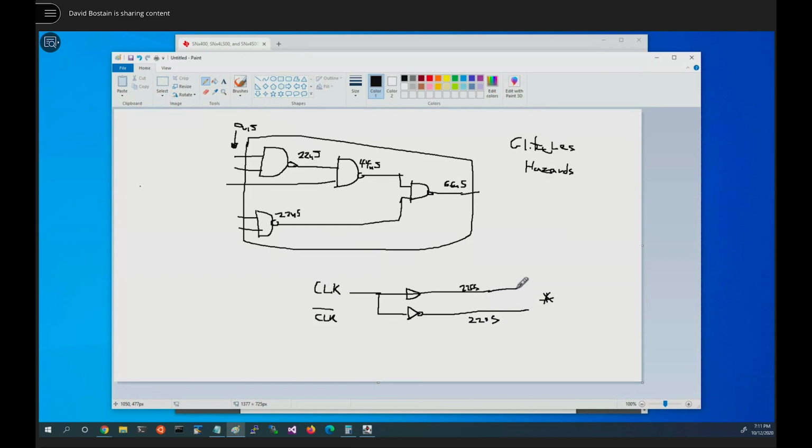That's something you would worry about if you were designing a digital circuit and you had to operate fast. You also care because if you had two signals driving another one that looked like this, and these two times here were assumed to be at the same time, but you generated something that looked like this on the output, and that signal said launch the missile, you just created some bad times.